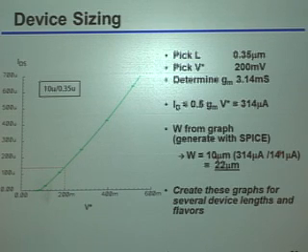Okay? So in other words, I'm again just using essentially SPICE as a lookup table to tell me for a given V star, what is the current density of the device? And once I know that current density, if you tell me how much current you want, calculating the size is trivial. Does this make sense to everybody?